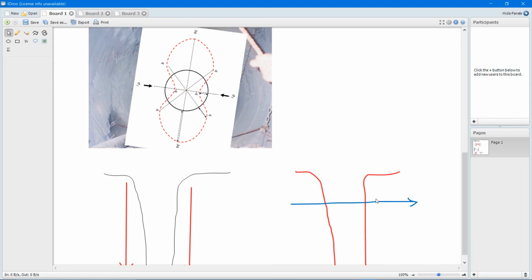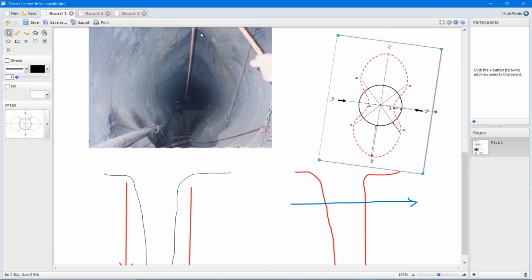And then on a section view, you'd still see it here. So what it does is that it's causing a lot more stresses here on the edges, right? Then your hole will lose shape, and then you end up with this shape, which is what we call dog earing. So whenever you see this, it is a consequence of a horizontal stress which has been acting.